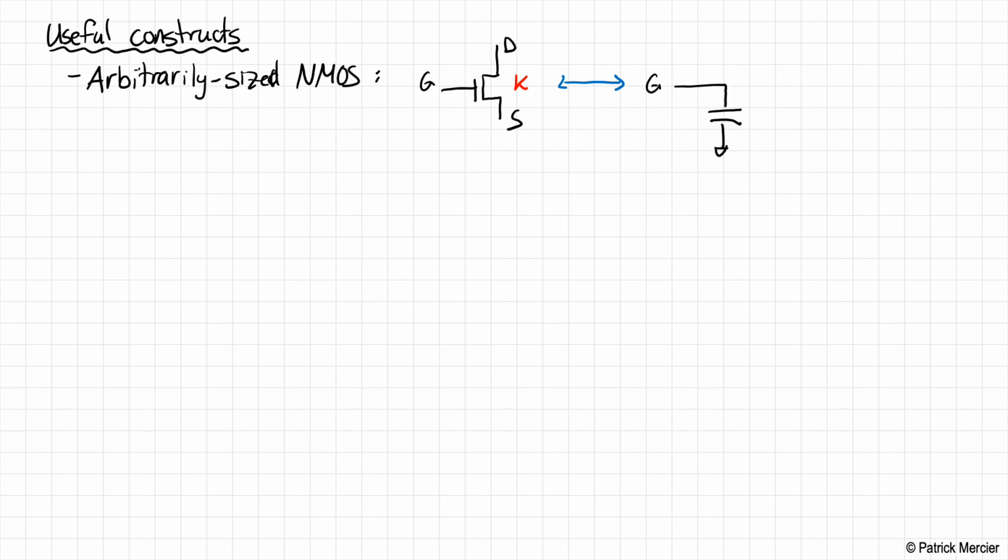We have some parasitic capacitance here that activates our switch. This is our switch model. It goes to our source, which has some capacitance on the source side. We have some resistance on the drain side, and we also have some capacitance on the drain side. Okay, so we're going to say that if this NMOS transistor is of size K, then we have Kc capacitance on each of the nodes here, where C is the nominal capacitance, and the resistance is of size R over K. Okay, so let's just write this down.